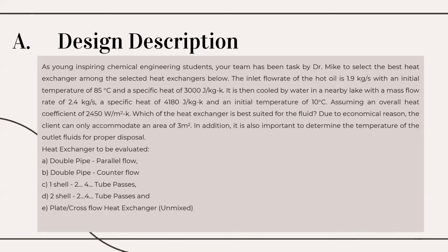It is then cooled by water in a nearby lake with a mass flow rate of 2.4 kilograms per second, a specific heat of 4,180 joules per kilogram Kelvin, and an initial temperature of 10 degrees Celsius. Assuming an overall heat transfer coefficient of 2,450 watts per square meter Kelvin, which of the heat exchangers is best suited for the fluid? Due to economic reasons, the client can only accommodate an area of 3 square meters.